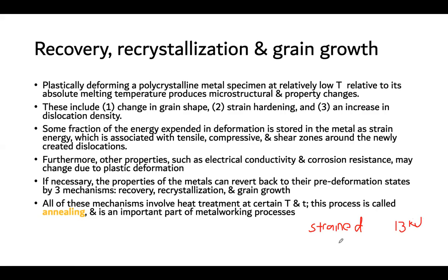The second one, the same piece of metal with the same composition, has been annealed, or normalized, if you remember the toughness video. So the normalized steel, I'm sorry, I didn't open my pad, I just brought my laptop, so it's not really good. I remember it's around 182 kilojoules, something like that, for the toughness.